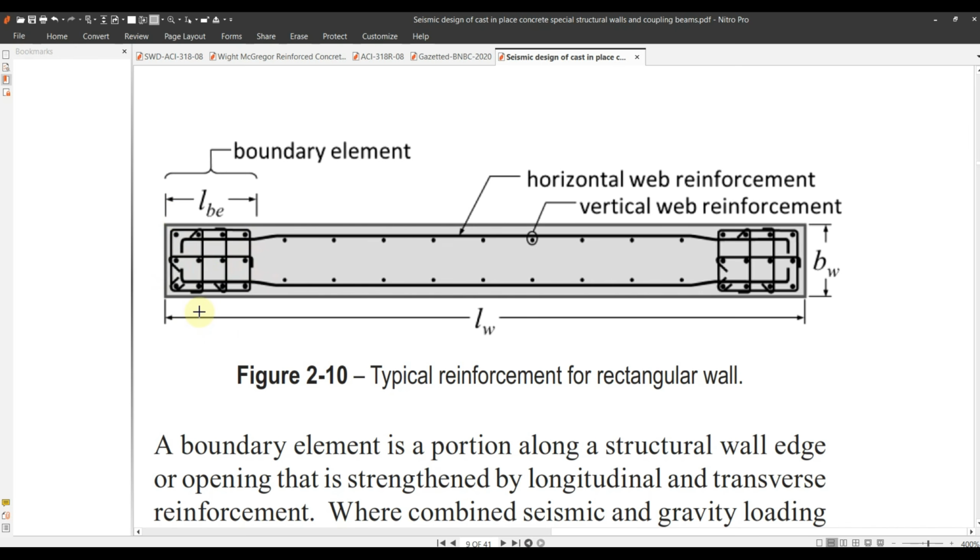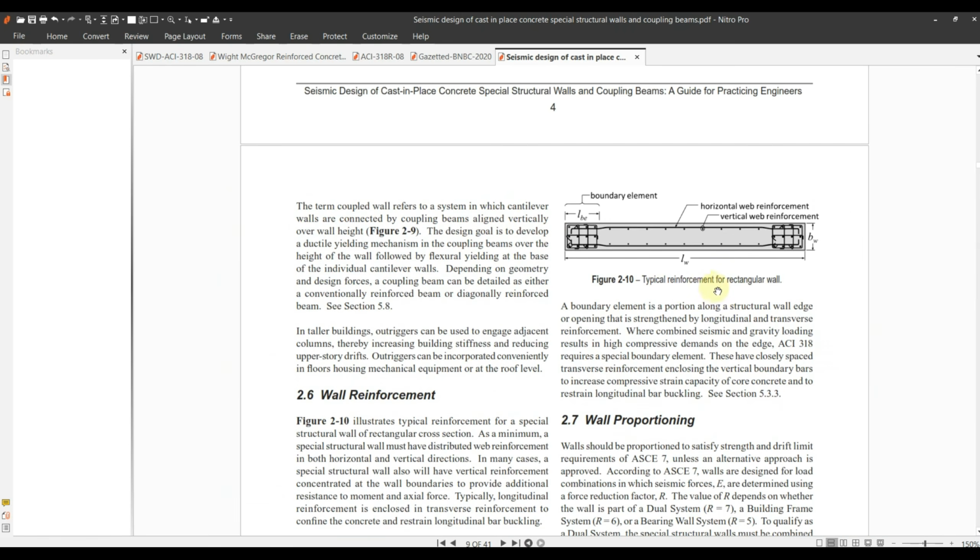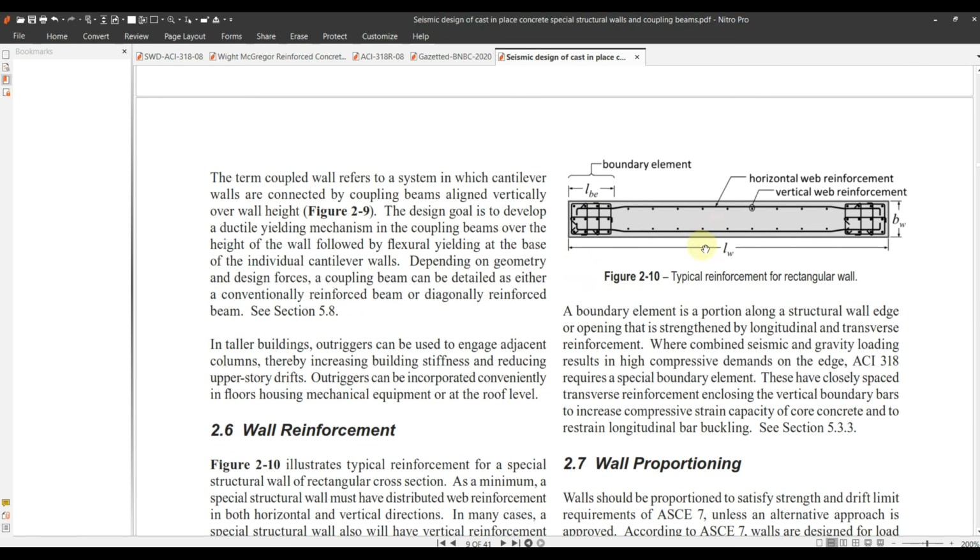to make the wall adequate. However, in the rest of the wall, the middle part, you may provide the distribution reinforcement, the minimum one. It may be 12 mm at the rate of 8 inches or 12 inches, etc. Or maybe you can design a general pier section in your ETABS model and then model this and the middle part as well, and ask your ETABS model to validate its capacity, whether it is okay or not. So there are a lot of ways to detail your wall.